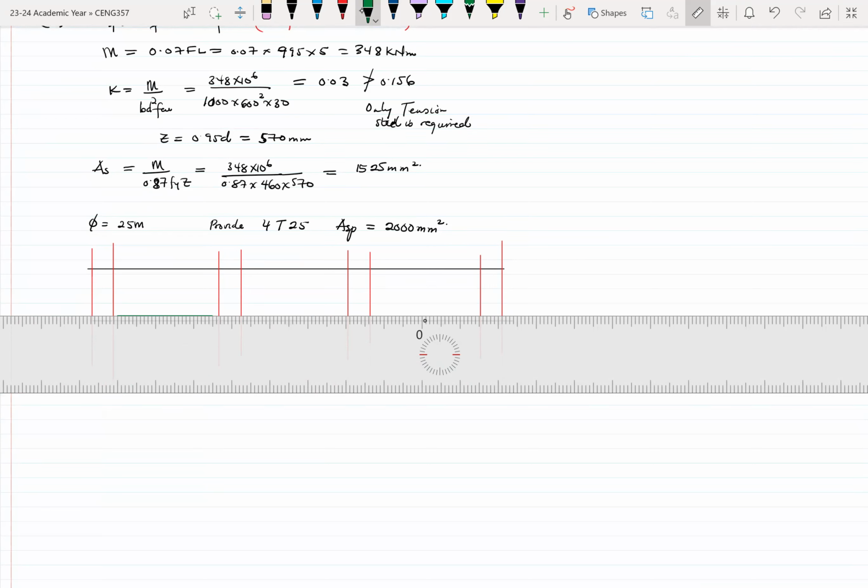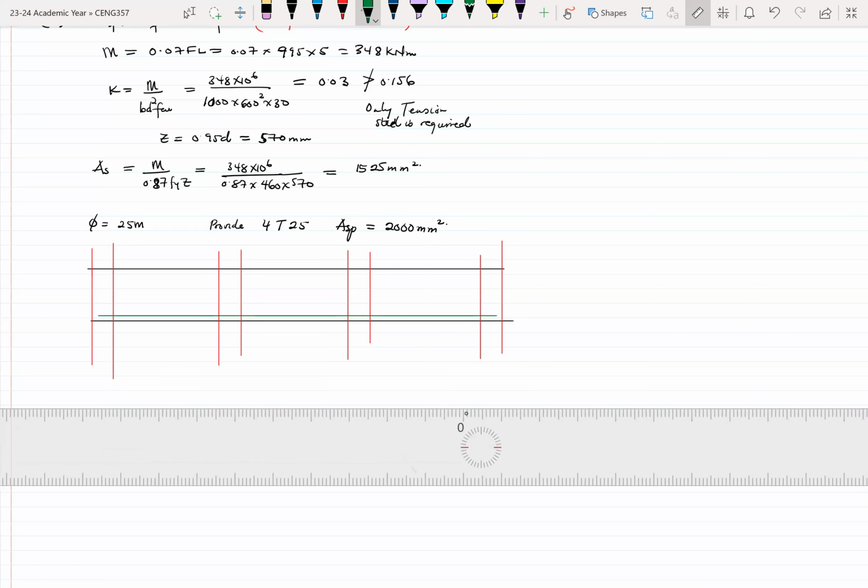We try not to cut too many rebar. So if both of them at the base share similar arrangement and size, we actually join them all together. Okay. But again, that'll be dependent on the length of the beam.